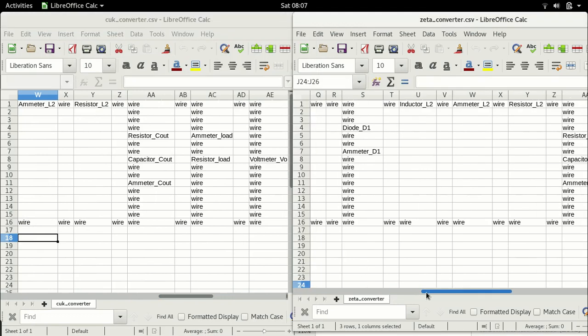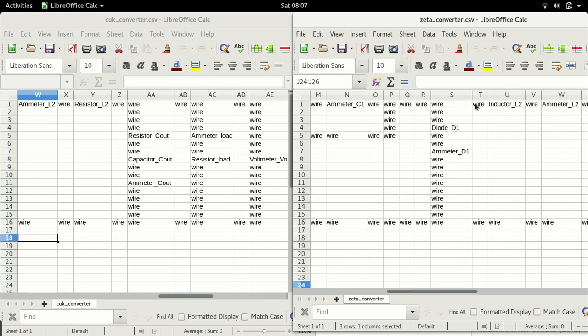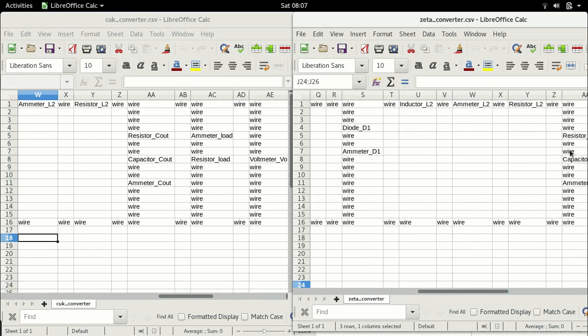And here also the inductor doesn't charge. The inductor freewheels through the diode and supplies the output capacitor. In this case, the current flows towards the right, because current in the inductor was flowing towards the right. It will continue to flow towards the right and it will supply the output capacitor in the clockwise direction. Here it is in the anti-clockwise direction.